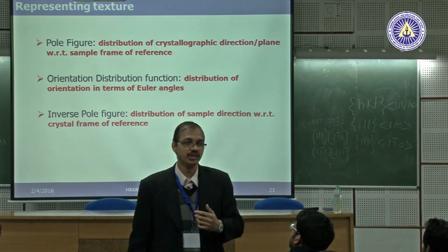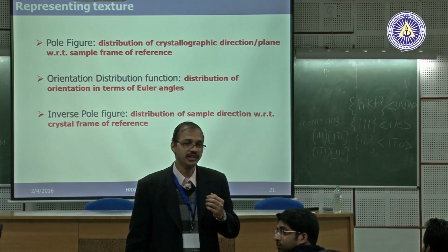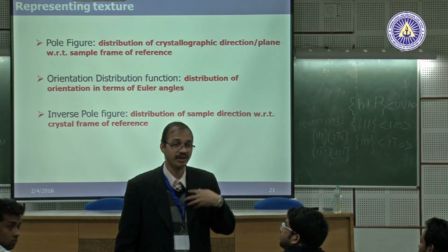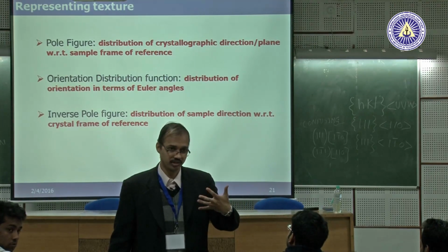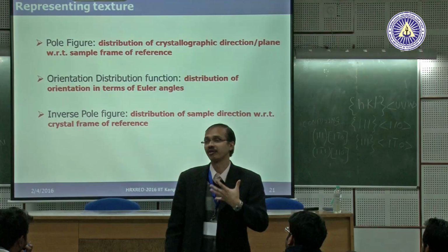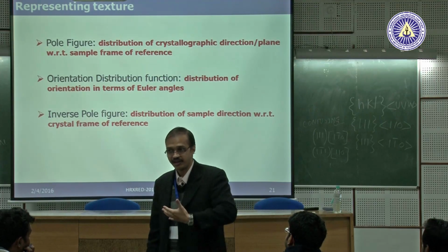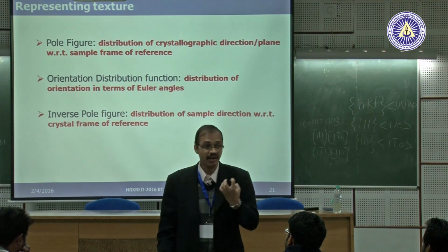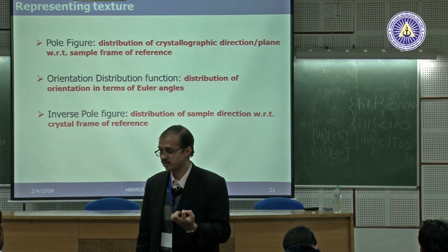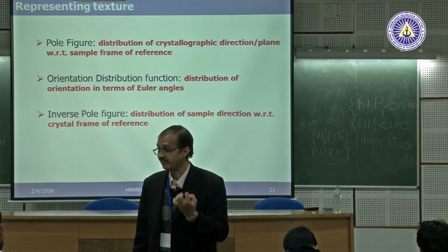We have Professor Suresh here from IIT Roorkee, and he will also tell you that it takes a few years to understand it. I'm still in the process of understanding how to read pole figures. So you have to develop it, and for that you really have to understand stereographic projection. Similarly for Euler angles. But remember the underlying principle: it is symmetry. The symmetry of your crystal gets reflected everywhere.